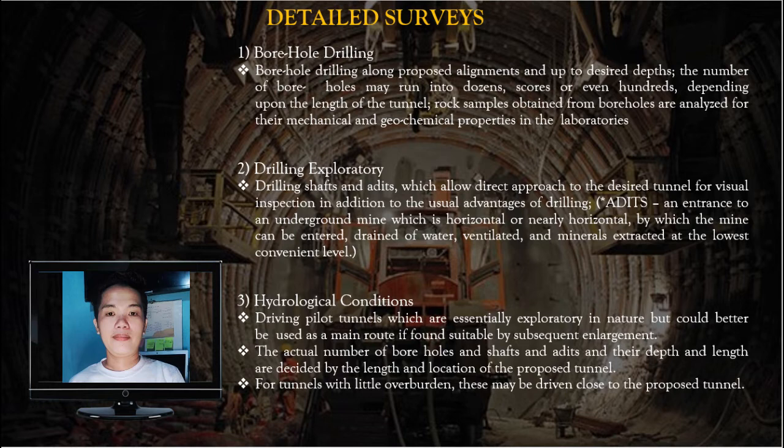The third one is driving pilot tunnels, which are essentially exploratory in nature but could better be used as the main route if found suitable by subsequent enlargement. The actual number of boreholes and shafts and adits and their depth and length are decided by the length and location of the proposed tunnel. For tunnels with little overburden, this may be driven close to the proposed tunnel.